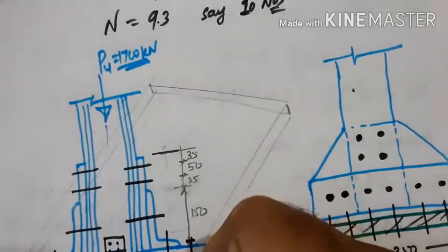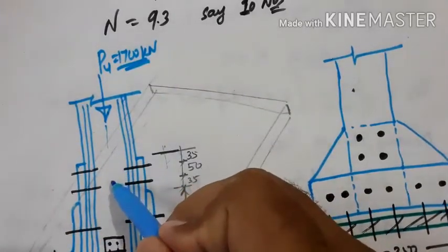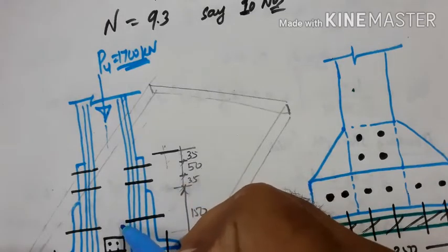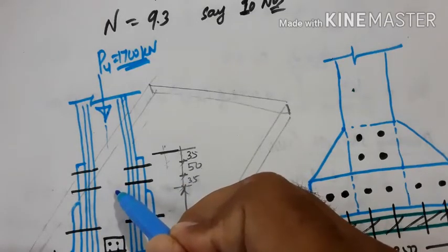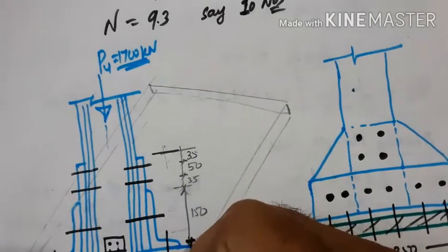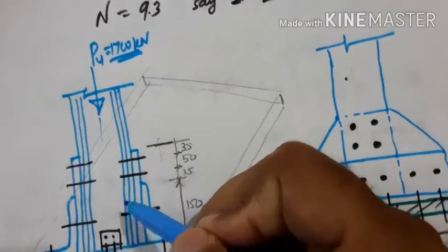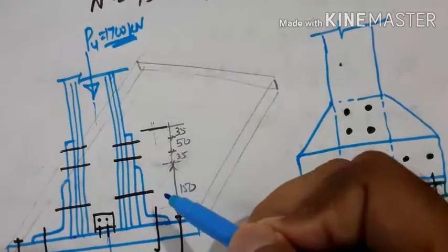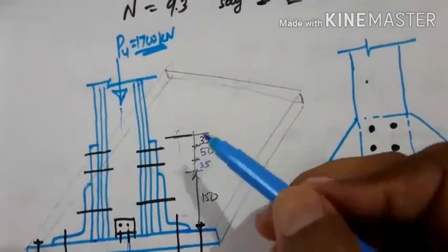When it is acting axially, the 50% of axial column load is assumed to be transferred to the base plate directly through bearing, and the remaining 50% will go through the connections. So these are the assumptions you have to make.